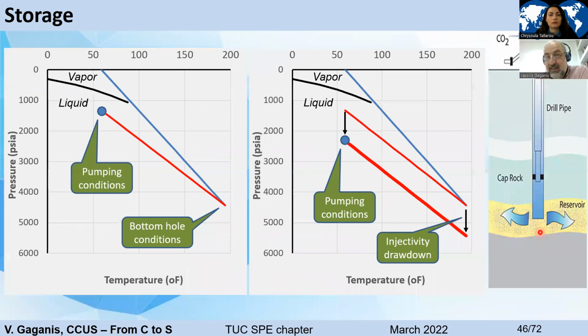Just think that by the time we inject the fluid here, it needs to exhibit a pressure higher than the static one so that it can flow. So it has to do with the so-called injectivity of the well. Now, if the permeability here is good, this will cost you only a few hundreds of psi. But if the permeability here is low, just remember the case of the shales that I discussed before. That means that you're going to need a lot of additional pressure here. To get additional pressure here, you need to have taken care of that at the top.